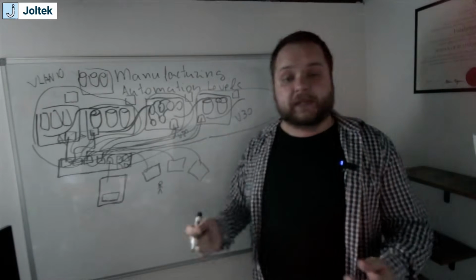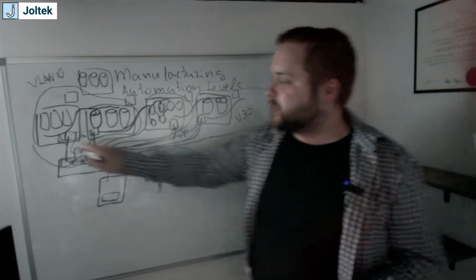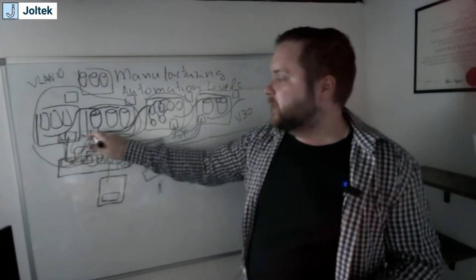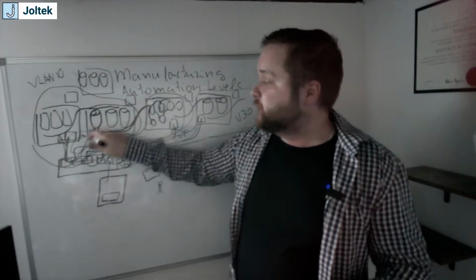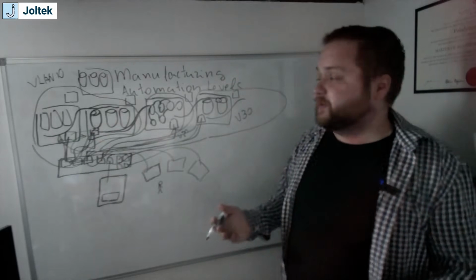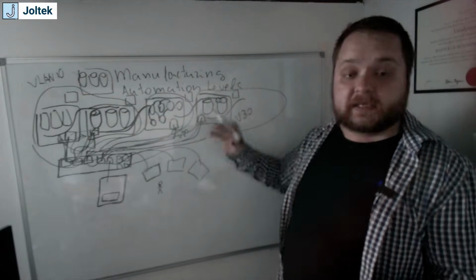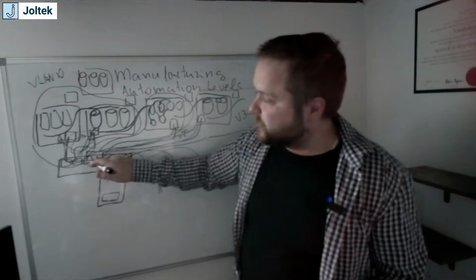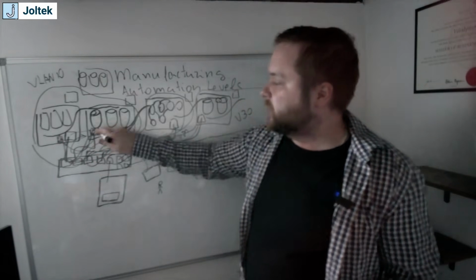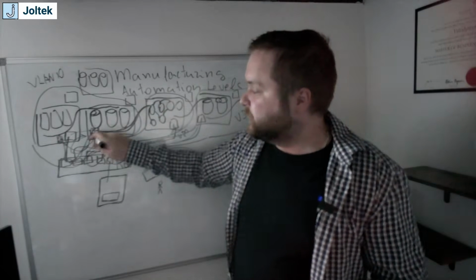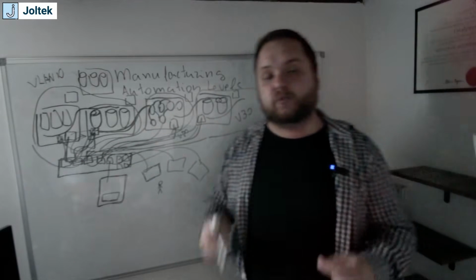Each one of those VLANs is going to operate as a separate subnet that allows the traffic, for example, between this PLC and this PLC. It allows the traffic from, for example, this load cell if you need to come back to this PLC for whatever reason. So basically, we've created a segmentation of 3 different VLANs in this example, but we do need the switch to say, hey, sometimes this PLC, which outputs to this system, needs to talk to the PLC in this VLAN 20, but only between the PLCs, right?